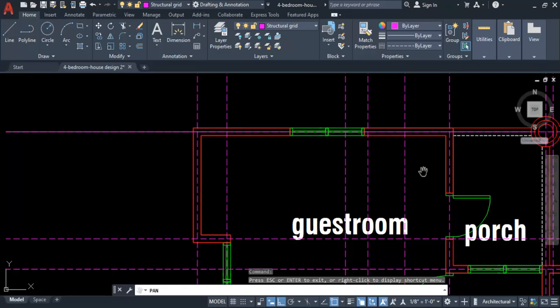So this is where as a structural engineer you have to contact the architect. You can discuss if the architect can change the thickness of the wall to at least 9 inches, because this is what we normally use. Or you also have to contact the client. So it depends on the budget of the client and all that. But if the architect decides to go with a 6 inches wall, then you as a structural engineer have no choice, although you still have to convince the architect. But in this case, let's say we have no choice, we are going with a 6 inches wall.